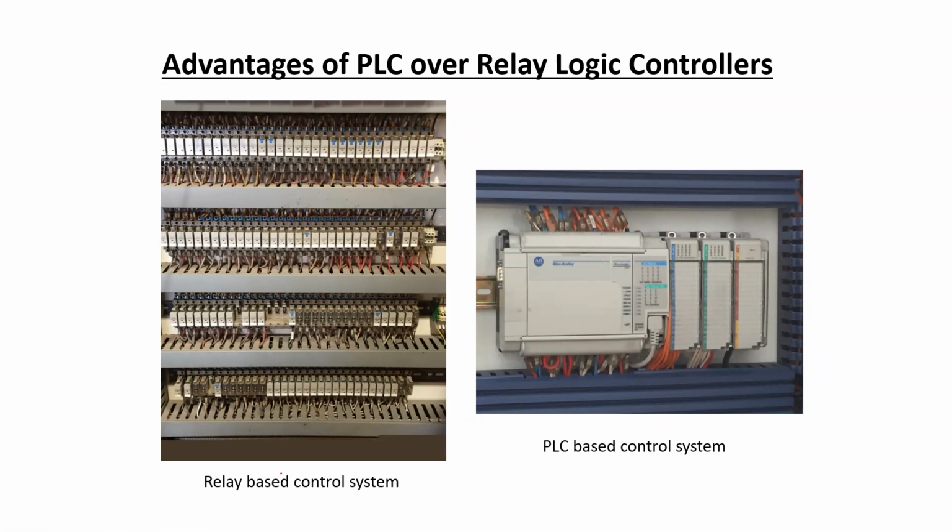In the relay logic control system, you can see that multiple physical relays are necessary, and the hardware connection between these relays becomes a challenging task. Also, the size of the control system is very large compared to a PLC based control system.